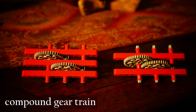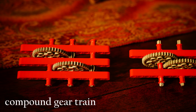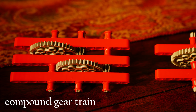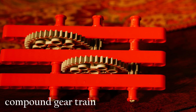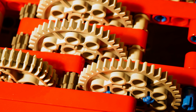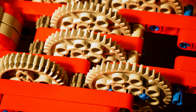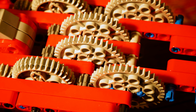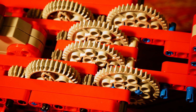Compound gears have two or more gears rotating as a single unit on one axle. Compound gear trains contain one or more compound gears and are typically employed to increase either the speed or torque of the driven gear, in which case the size of the gears of the compound gear will differ. Here, a large LEGO servomotor turns two 12-tooth double bevel gears, which in turn power two separate compound gears, and finally two 40-tooth spur gears that are attached to the lift arm. This arrangement of compound gears increases lift arm torque.